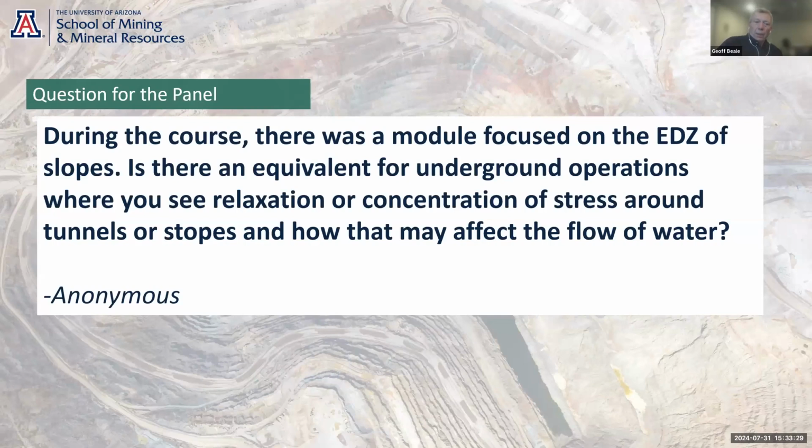Couple of examples. I'm involved in doing a decline at the moment, and unknown to them, they were mining it parallel to a structure. They started seeing very high rates of convergence in the tunnel, and lo and behold, they then had a slab failure. And it turned out they dilated the fault parallel to the decline, and water got in, and the force of the water had caused the side of the decline to fail. So that's one example.